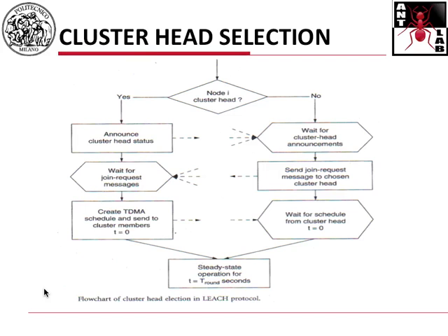In that paper, they were proposing to use some kind of TDMA medium access control within each cluster. But this is not related to the clustering process, meaning you can do whatever you want within your own cluster once you have it. For example, one very interesting thing could be to run 15.4 within each cluster, with each single cluster head acting as a point coordinator.